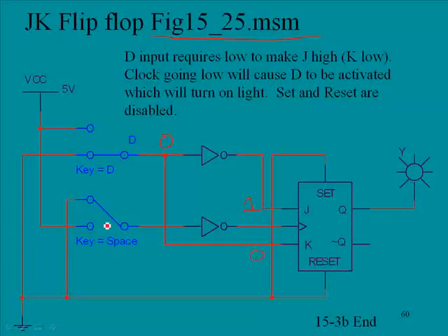And then the clock is going to be clocking on a positive edge, so this is going to ground, which puts a low here. It's going through the inverter, which would put a high. So we have a transition from 0 to 1 when we place that switch in place. When that occurs, the 1 should be passed through to Q, and the 0 should be passed through to Q-not.